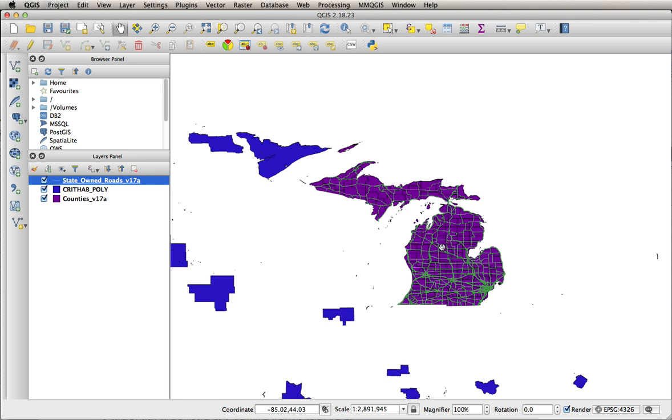We want a 1 mile buffer, or find the critical habitat areas that are at least 1 mile away. And the built-in analysis that comes with the QGIS actually uses the same unit of measurement as the coordinate system. In that case, it's the latitude, longitude, or degrees are not going to work.